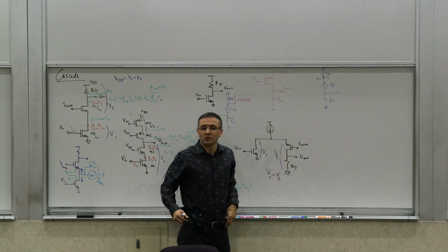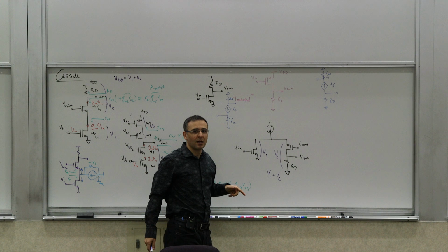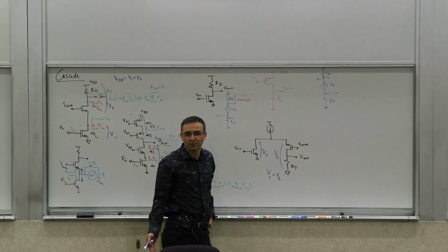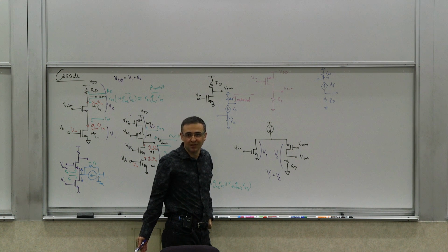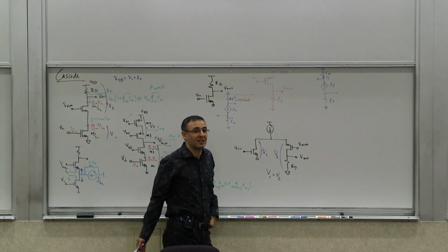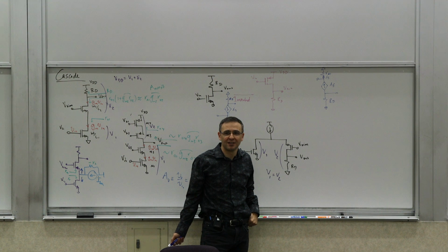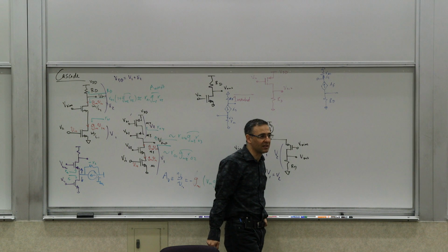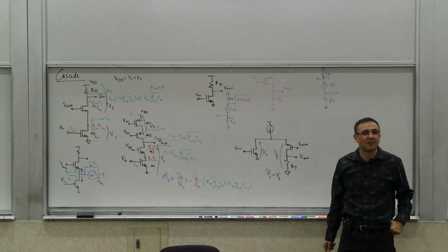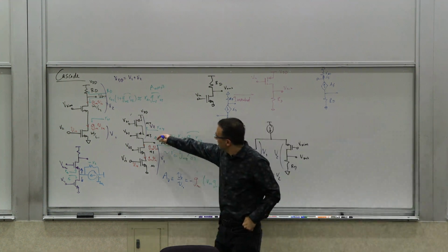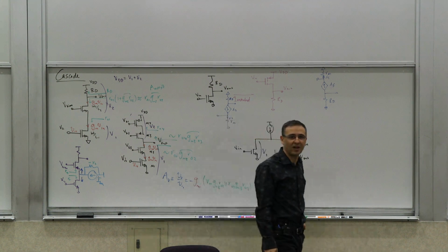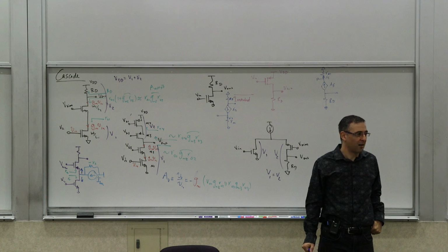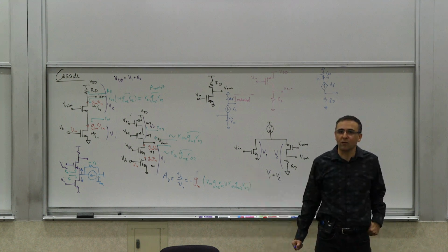And if it tells you, yes, this is a source of worry, you're still not done. We will see we can actually make better current sources whose output resistance is higher than RO, right? We even have that topology on this whiteboard, if you want to think about it. If I want to get something higher than RO, where do you see something higher than RO in the stuff that's behind me? A cascode, right? Exactly. So these resistances are higher than RO. So if you really want to make something with higher output resistance, you can use one of these cascodes. Of course, there's a trade-off there.